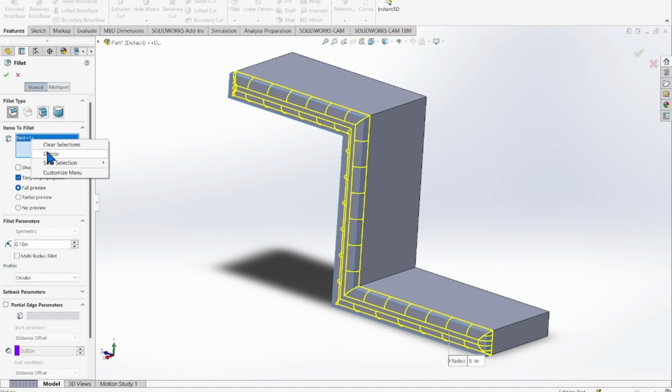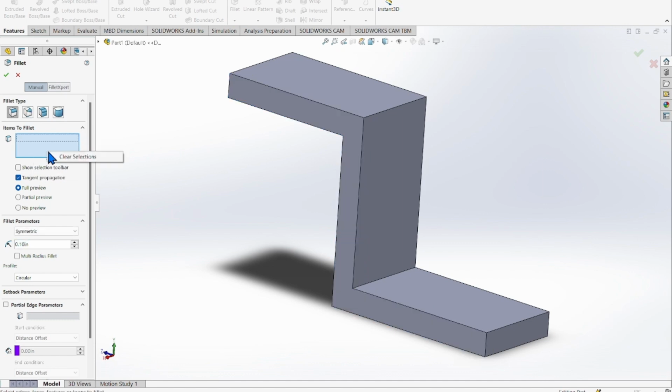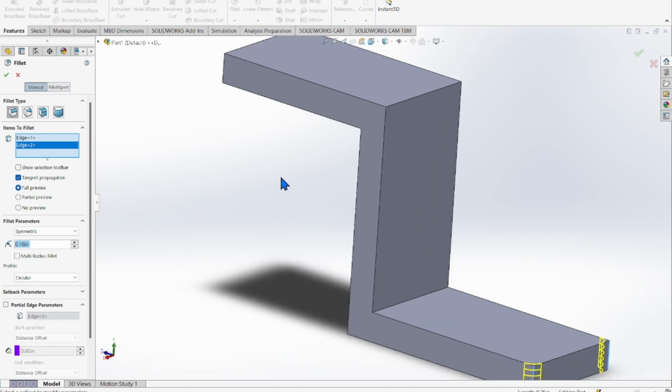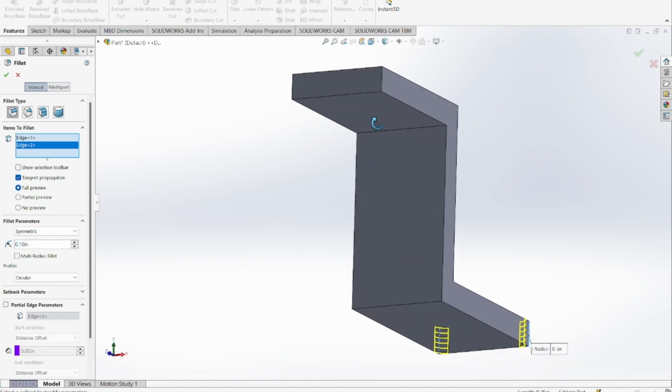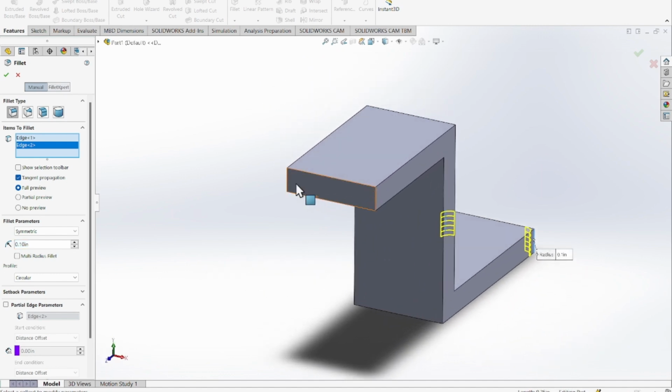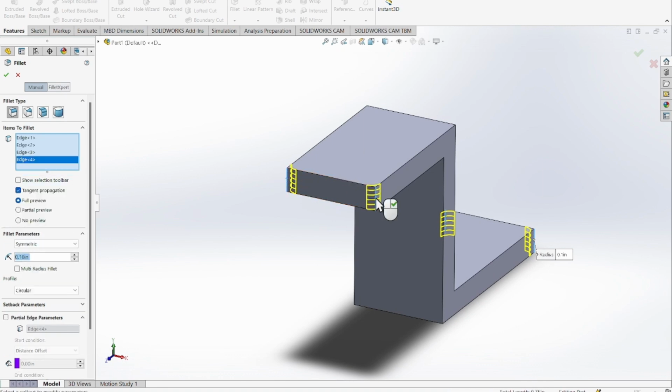So I'm gonna clear this one or delete this. This one you just right click it and you have those options right away. But I want this to be right here on this line. Right here too as well. Then with your mouse, I can use the middle scroll, click it or push it down. You'll hear it click and you just drag it around too as well. Click the same spot too as well with the lines and it'll begin to do fillets.